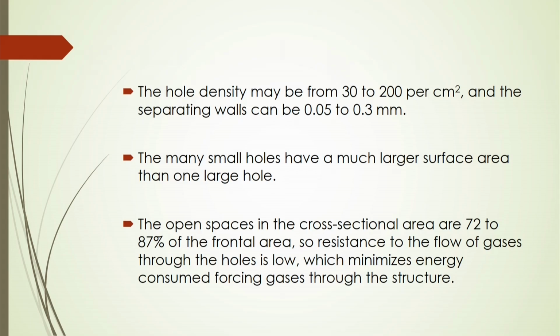If you have small bores or holes, the pressure drop will be higher, but then you have to think about what type of liquids are being used and also how the channels are made. So, there will be optimization based on the different variables of the operating conditions, based on which you can design the monolithic structure and get process intensification.